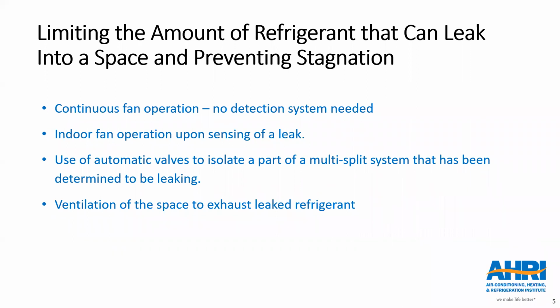So the key to preventing a leak of A2L refrigerant from becoming a fire risk is the use of air circulation by the indoor fan, coupled with limits on the amount of refrigerant that can be released into the space. The indoor fan keeps the refrigerant from accumulating near the floor, and in cases of ducted systems, distributes the refrigerant to all the rooms, ensuring that the concentration is well below the LFL.